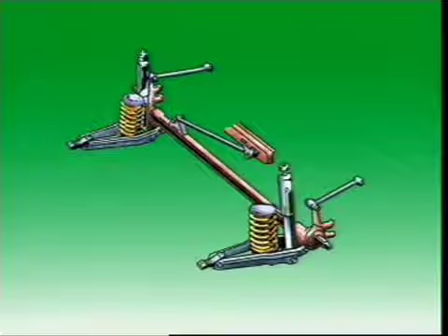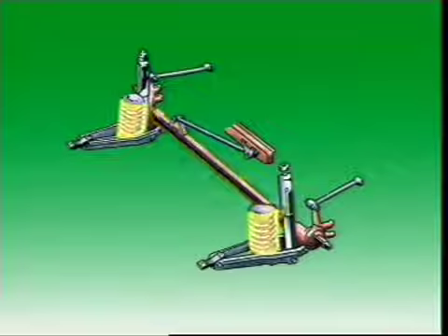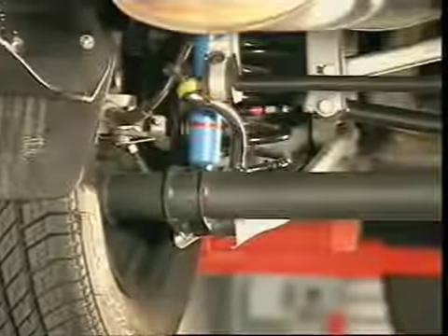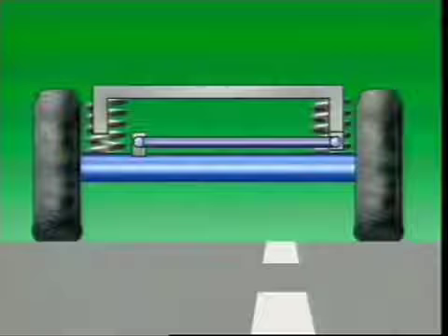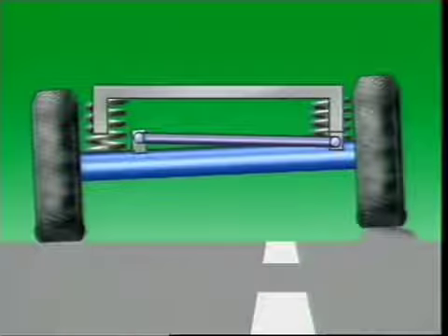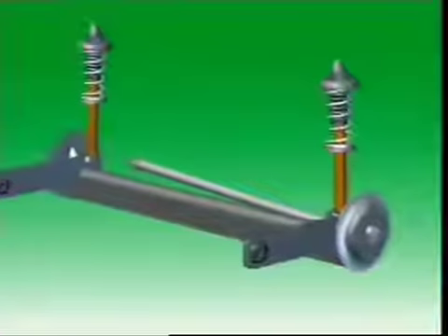On front-wheel drive vehicles, a simple beam axle can be used on the rear with coil spring suspension and control arms for location. This is called a dead axle, since it only supports the vehicle and doesn't transmit any drive. It is also non-independent, as deflection of a wheel on one side of the vehicle will be transferred to the other wheel. This can be reduced by using a U-shaped axle beam with a torsion bar mounted inside it.